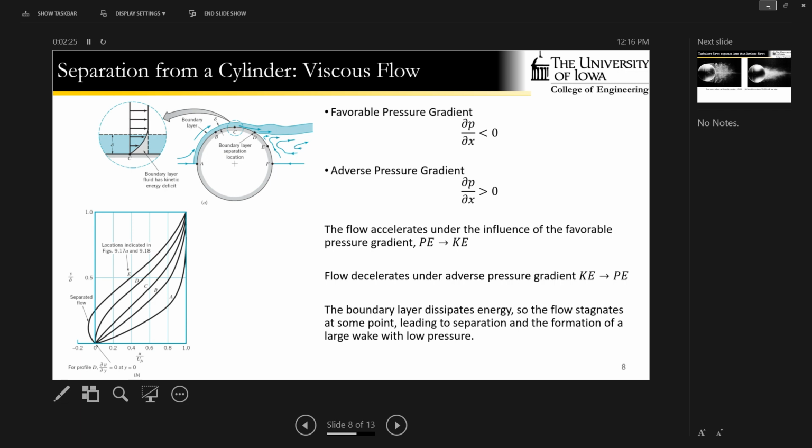So when you hit point C there, that's usually going to be the point of minimum pressure, maximum velocity. Now, if the flow didn't have any viscosity, if it were perfectly inviscid, lossless, Bernoulli would tell us that from point C to point F, it would then slow down again and regain all of that pressure. Basically a perfect energy balance.